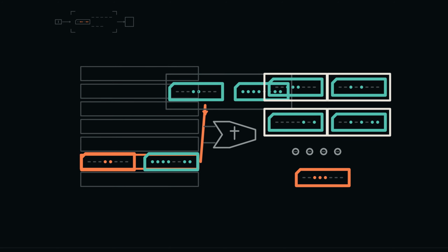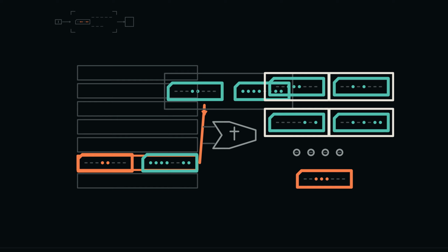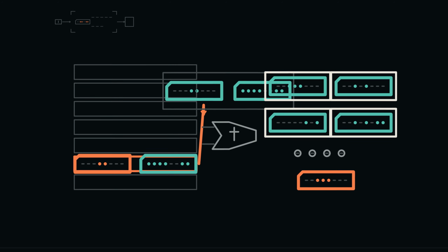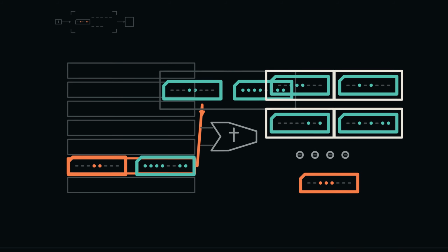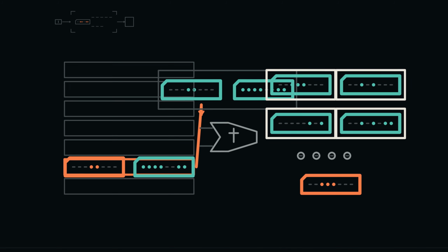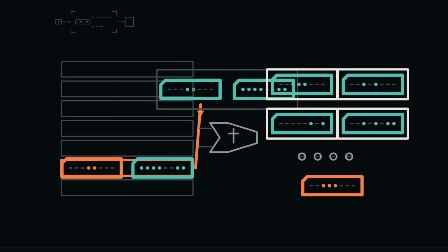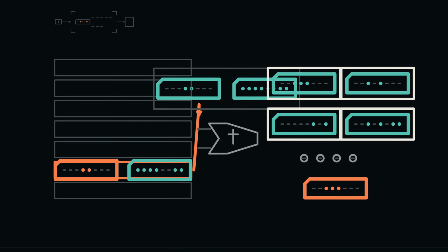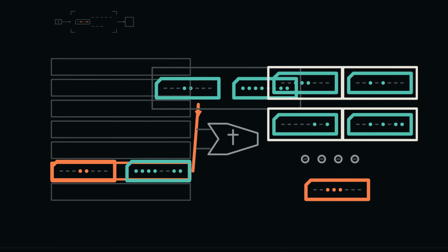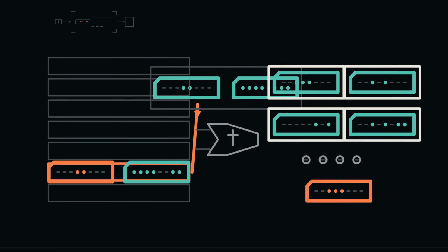To display a digit, the program reverses the offset operation. Adding hexadecimal 30 to numeric 8 produces hexadecimal 38, the ASCII subset, and UTF-8 byte for the character 8. A store instruction then places the display data address in the memory address register, copies R0 into the memory data register, and commits that byte to the selected device register.